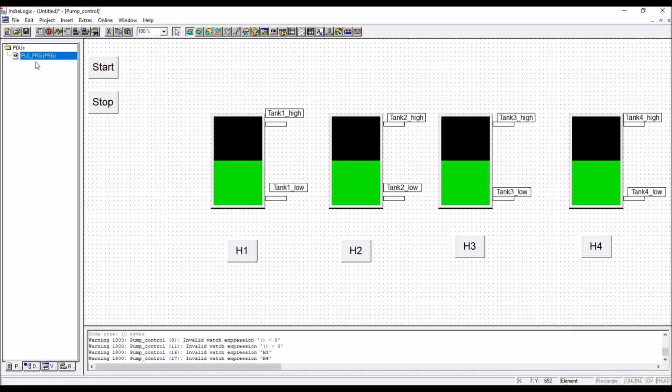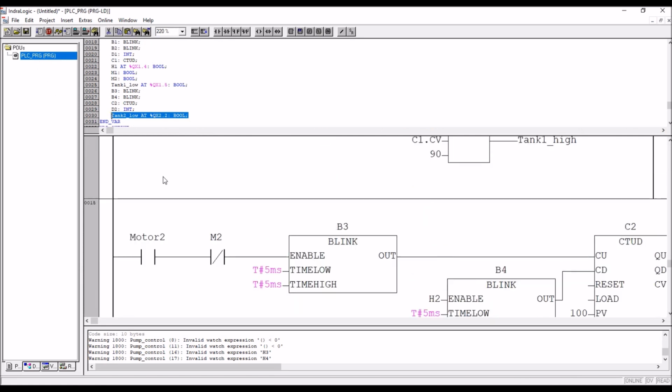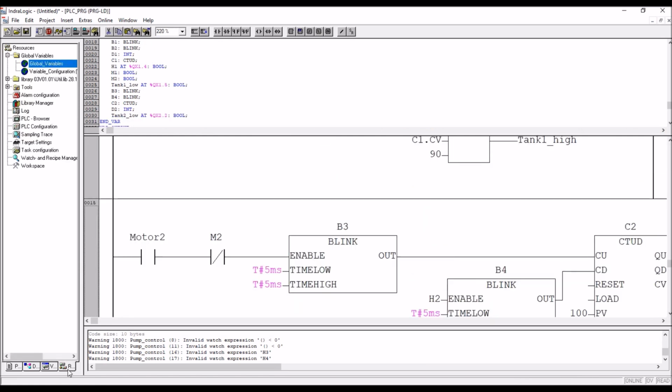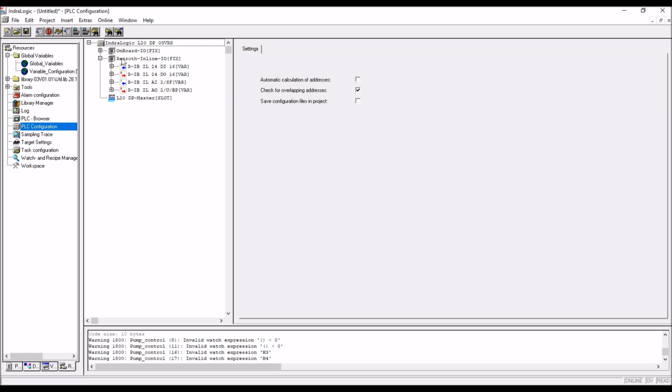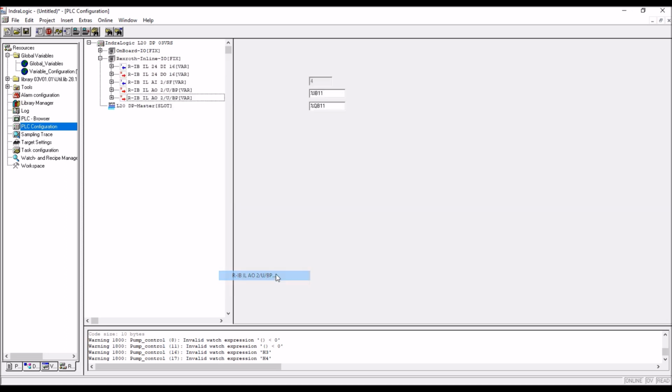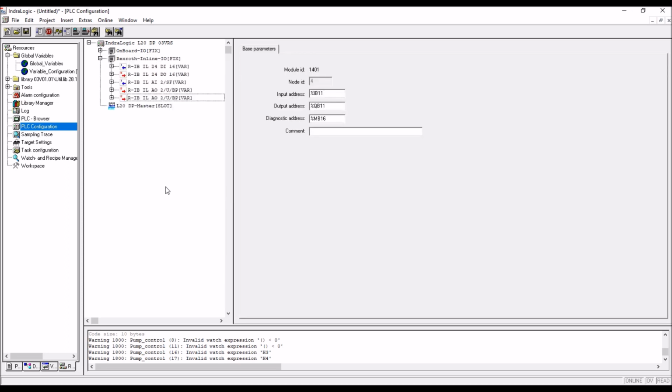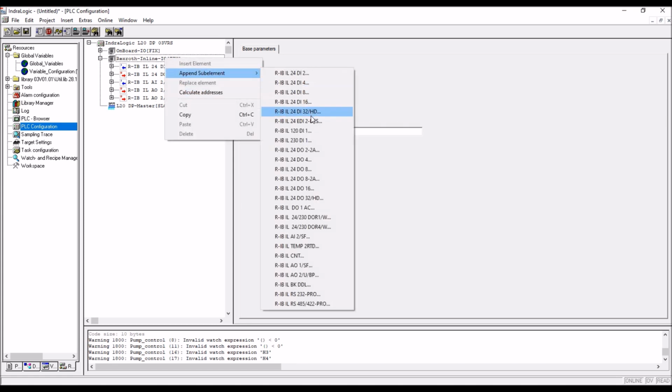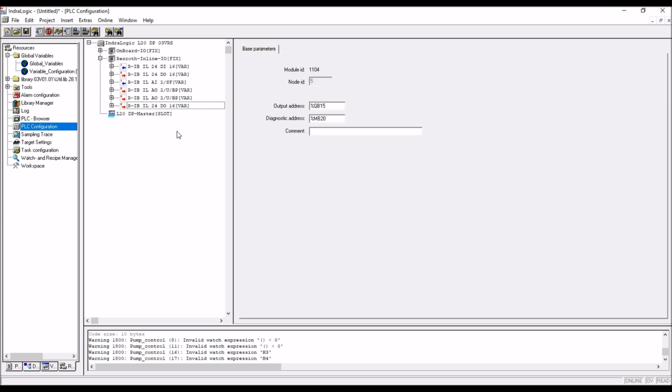Again, same thing. We have to repeat. But here analog output we have already taken 2, it is already over. So go to PLC configuration, you add 2 more analog output. So total 4. Okay. Even inline also got over, right? So we can add one more DO16, we can add one more. But here sequence is not important because we are not connecting to PLC.